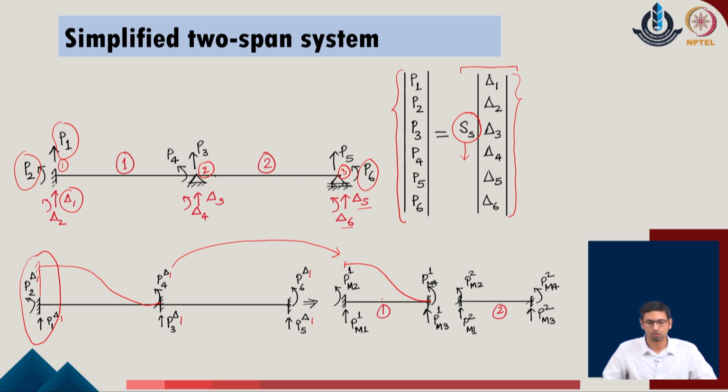Now, what it also highlights is that as I identify the deformation in the given direction with respect to a value of delta 1, I will also be able to calculate the member forces corresponding to the 4 degrees of freedom at the ends of the 2 joints of the given member. Similarly, the second member is not undergoing any kind of deformation, so I will also be able to evaluate the member forces corresponding to this member, and they are 0 for now in the given condition.